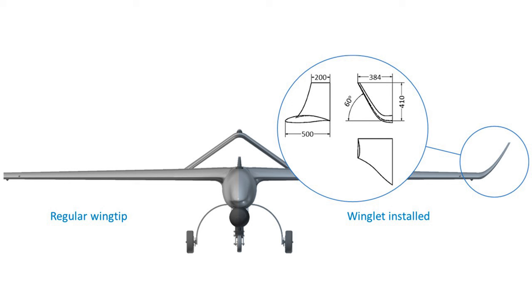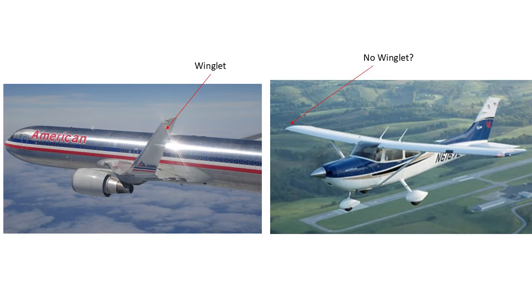However, if the aircraft in question is already small and must take off from short runways, then the weight addition in the non-lifting condition or during takeoff while still on the ground will be a bad thing, as the minimum distance for takeoff will be increased because the aircraft has to accelerate more weight to a faster takeoff speed that generates more lift. You may have noticed that a lot of the larger planes like commercial airliners have winglets, but smaller planes tend not to have winglets.